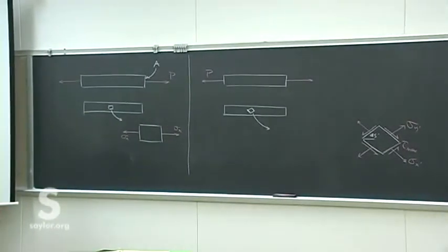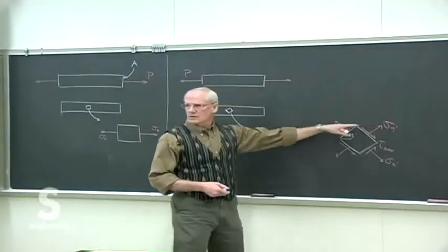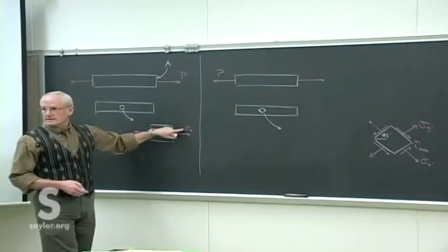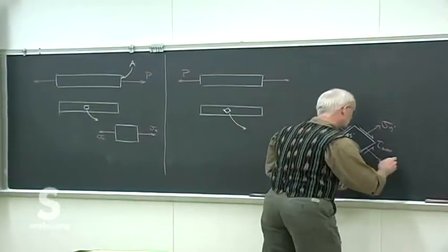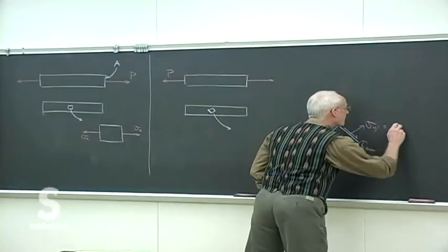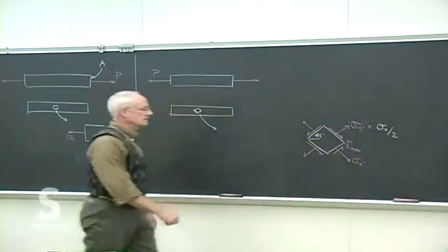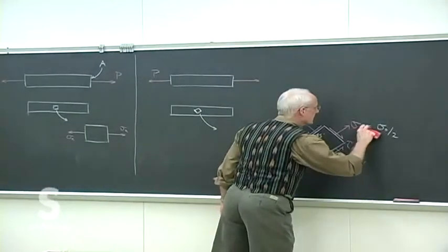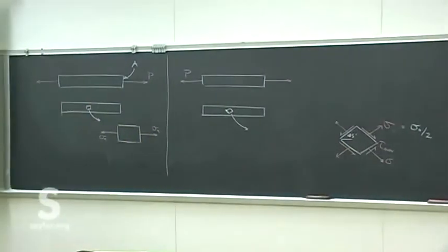Anything other than that, any other arbitrary angle, we're going to see less shear stress. Remember what the magnitude of these normal stresses were, relative to the original normal stress? Half. It was half of the original. In fact, those two would be the same. Sigma original divided by 2. I guess if they're going to be the same, we don't need any kind of subscript on them. Okay.